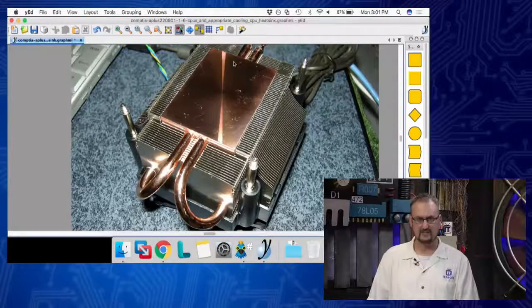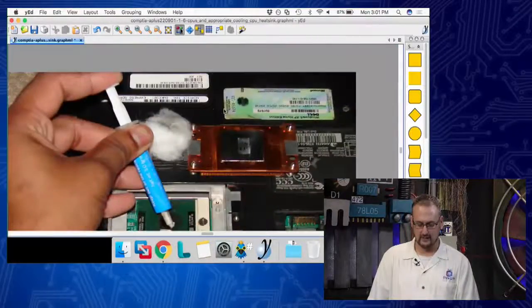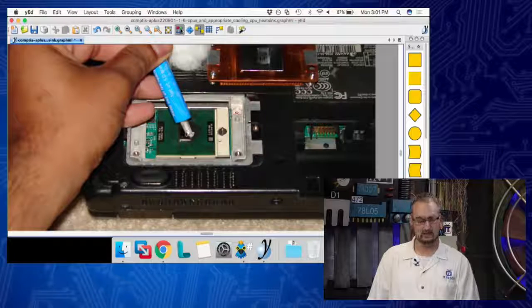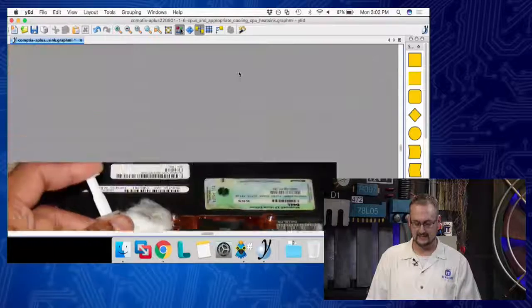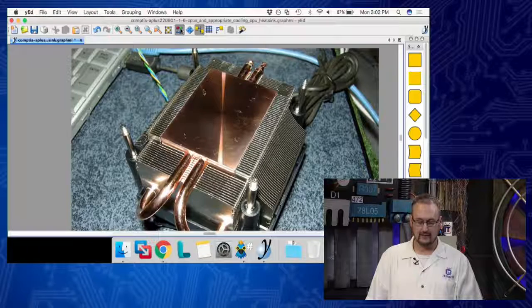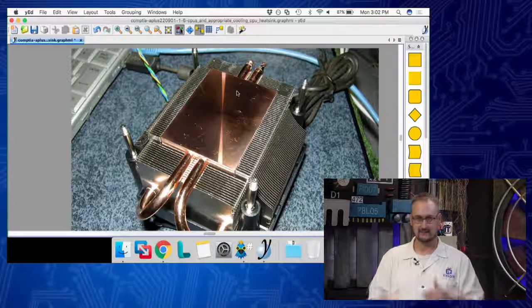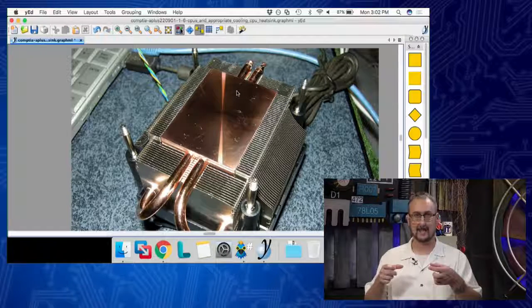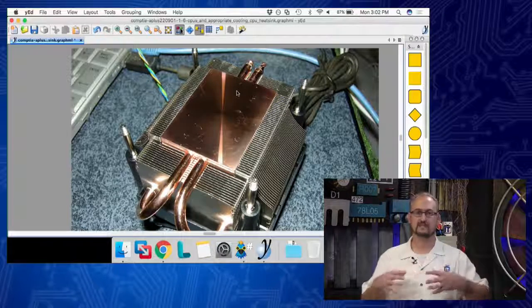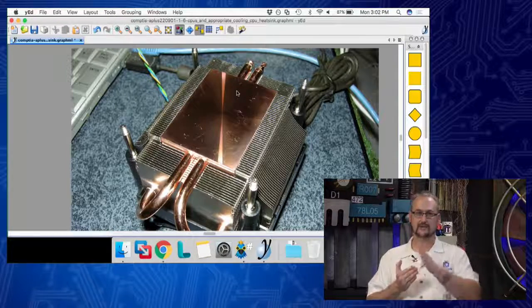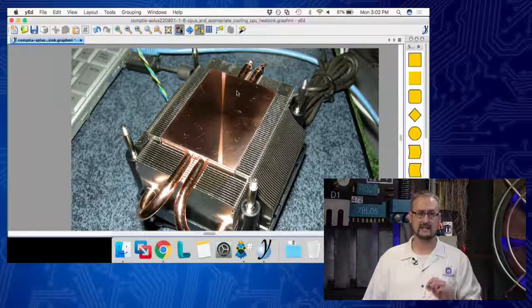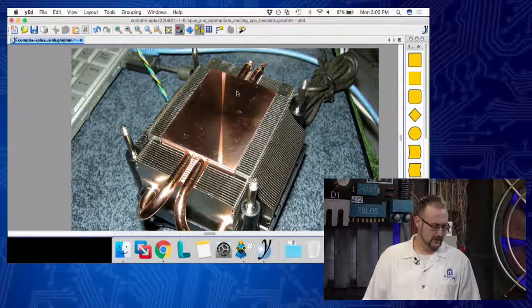But when you're putting, and let me show you here, guys. So I got another heat sink here on the diagram, and you'll see that, again, we've got this surface right here, and this technician right here is putting that thermal compound, in this case putting it a little rice-sized, that'll do you by the way, on top of the CPU, but you also put it over here on the heat sink, and this is a laptop one. So that thermal paste, if you will, that thermal compound sits in between the heat sink and the CPU, and it bridges that gap, the imperfections, the milling marks, and what it does is it helps to dissipate, to pull that hot air from that CPU, and helps the transfer of essentially the heat into the heat sink as well. So do also know that.